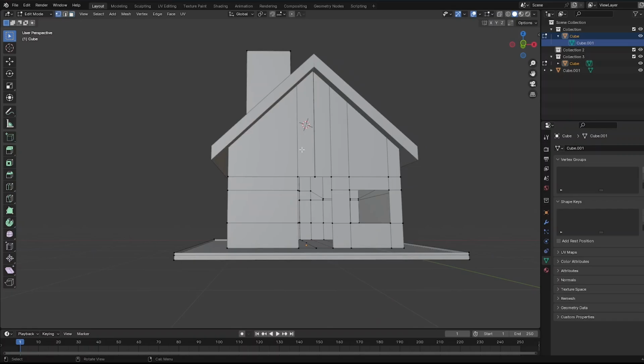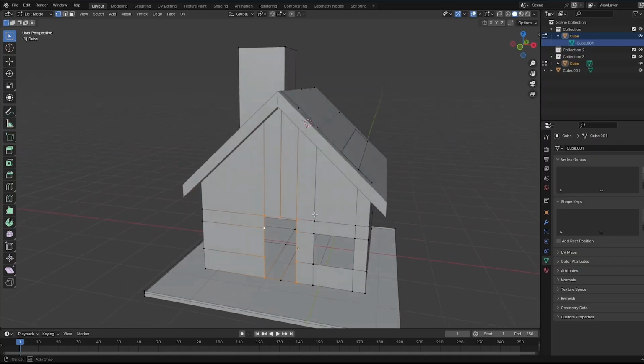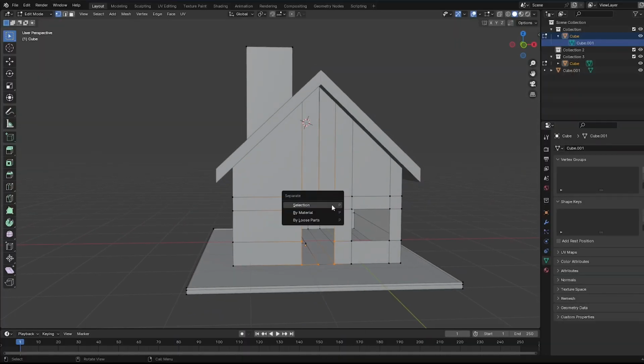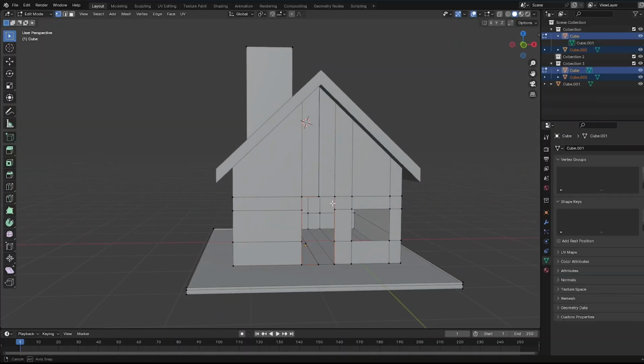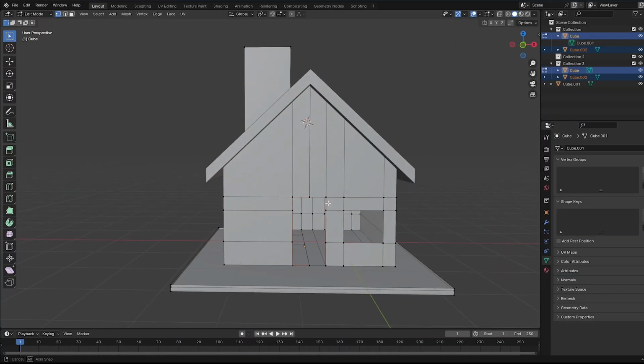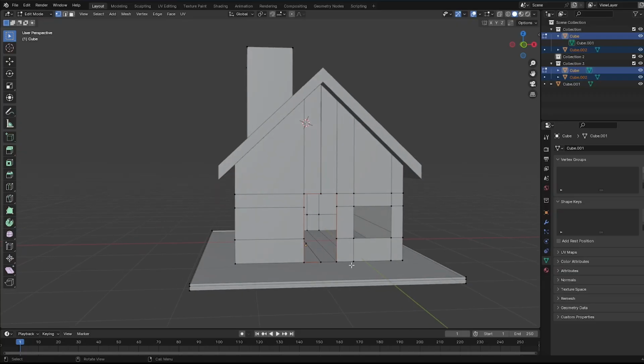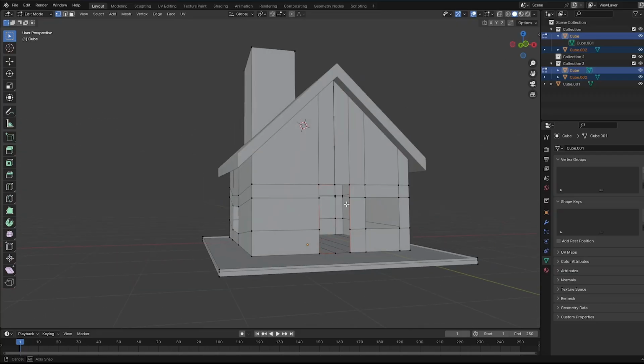So I'm going to click on this vertices option, click on them. There we go. We can see the bottom right now. And then you're going to press P to make a selection. And there we go, it has turned into a shape. Now, if I press E, I'll be able to apply the extrude over here.